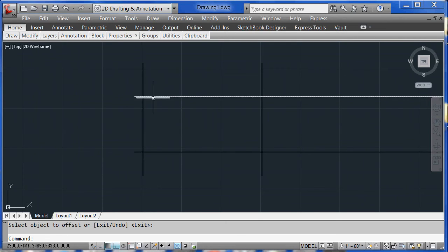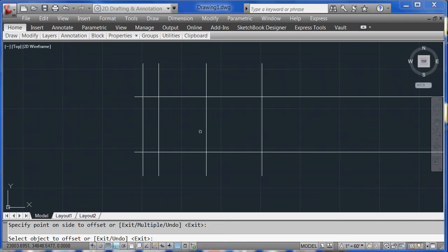Now what I want to do is add this wall thickness right here. Okay, and according to my picture, it looks like it's 1 unit off. So I hit O, hit return. It still says 7.5, but I just want it 1 unit here. And I have to take a measurement to where my next exterior wall is right here. And it looks like it's about in the middle of the piece. And it is 1, 2, 3, 4 over. Okay, 4 over from this edge. So select the offset command, type in 4, go over 4.